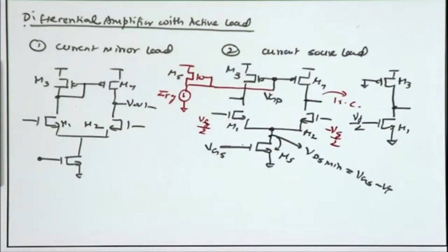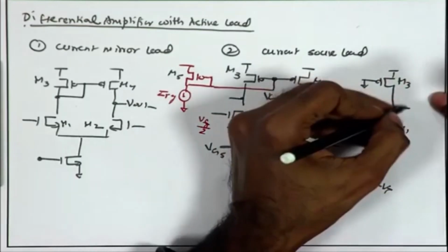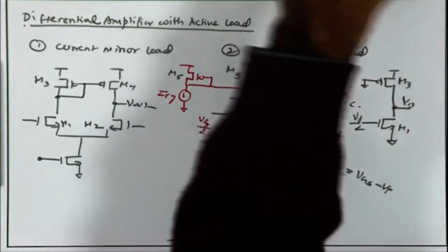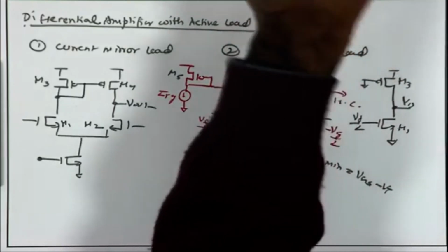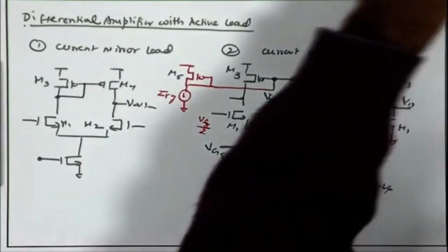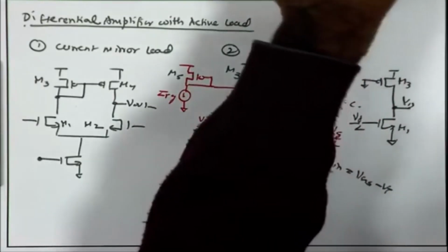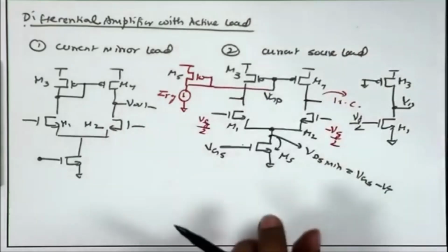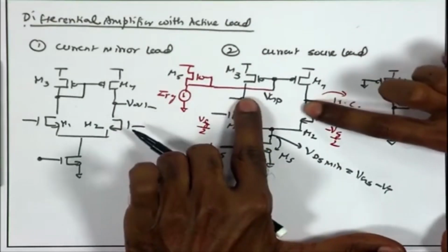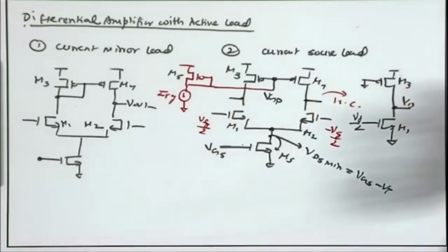While discussing the single ended common source amplifier with active load, we discussed a problem that Vd is very ill defined. We do not have a very good control of Vd. If we recall our derivation of the Vd, we saw that Vd is strongly dependent upon lambda, and therefore it is not a very well defined quantity.